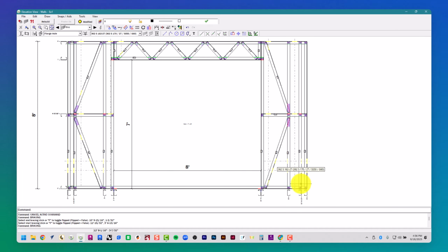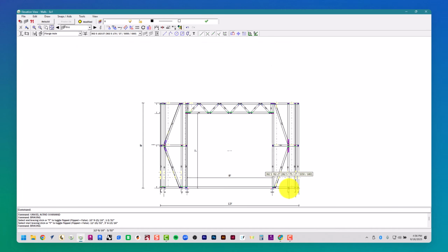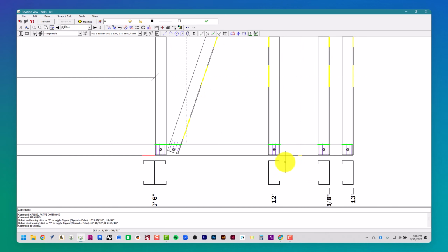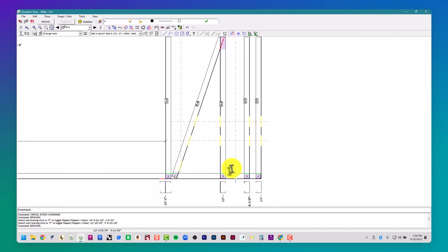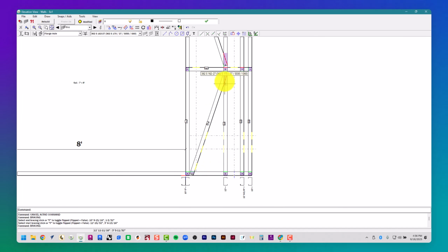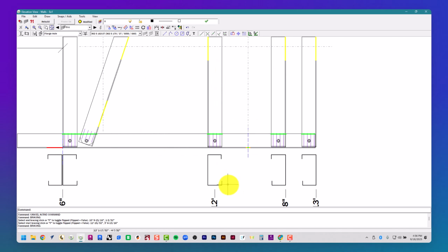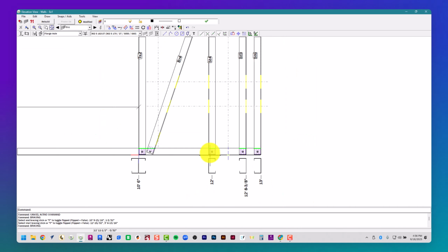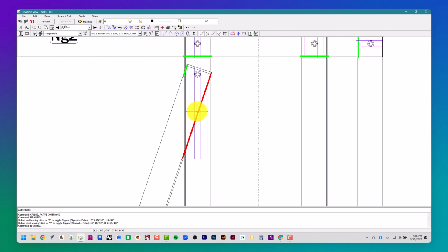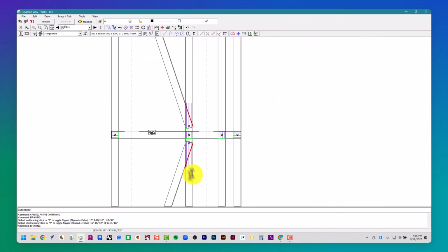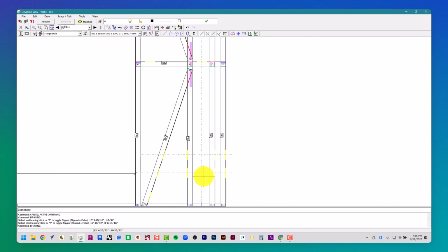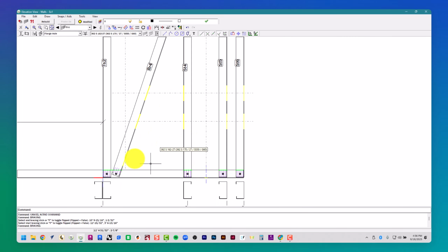We need to fix this stick because it's oriented the wrong way. With bracing entering the web of this stick, which is this back side, it causes some weakness in this stick. What we want to do is flip ST4 to turn the opposite way, and we can use the flip stick command to do it.